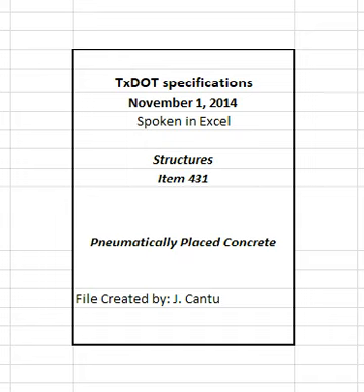The mix design will be approved when the average strength of the 3 cores conforms to the strengths shown in Table 1. Provide additional test panels as directed if there are any changes in materials, equipment, or nozzle operator during the work. 3. Construction. 3.1 Qualification.